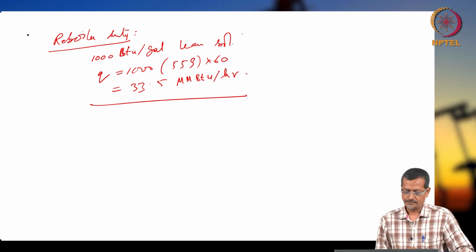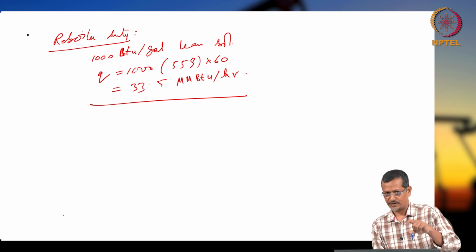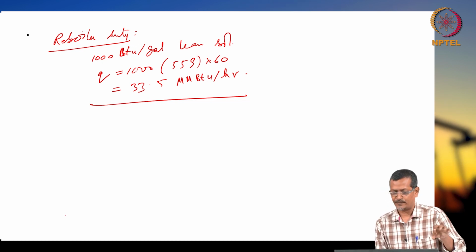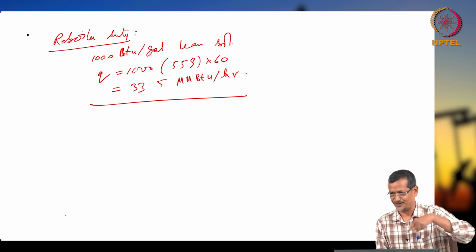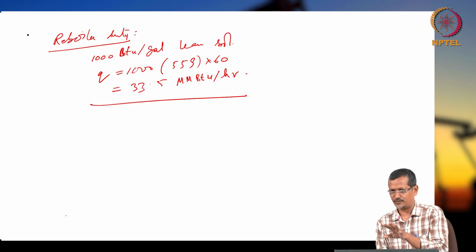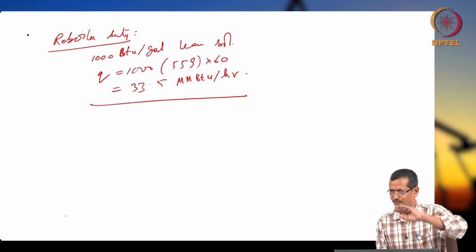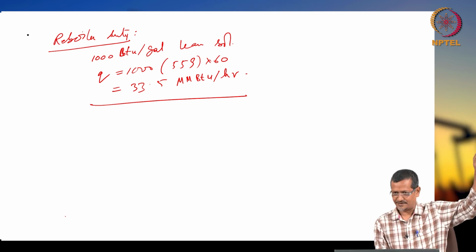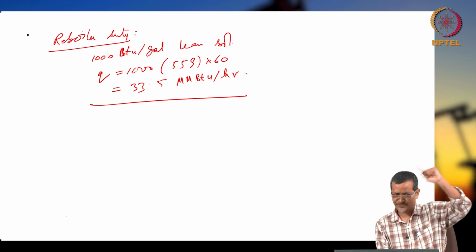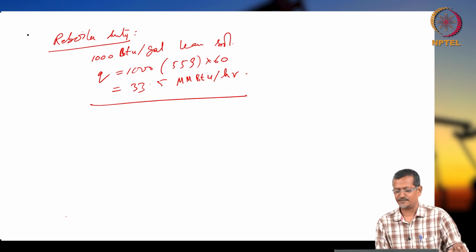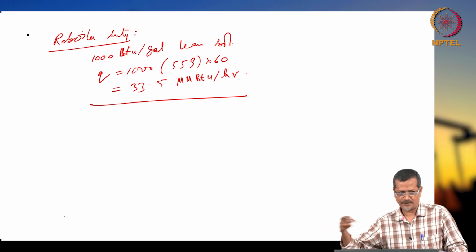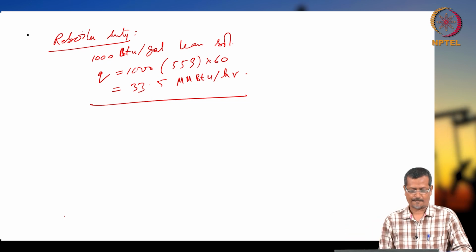Okay. So reboiler heat duty is how much heat will be required in the reboiler. Some heat you can recover, some heat you cannot recover. If you assume that we are recovering some amount, then you have to do more calculation. So for simplification, you should just get the idea. This much heat will be required, and this amine will flow to your absorber. It will come again to the reboiler, and again go to the absorber. So the circulation will go on. Whatever extra acid you are producing will get separated, and you can reuse or dispose of it.